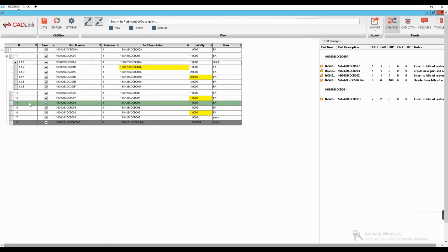So we have a gray line over here. This is a new item. That means this will be created in IFS later on. If we go into the unit of measure over here, there we can change the unit of measure. The drill down you see here is the drill down of the master data setup in IFS. So we only take data out of IFS to make sure that you get 100% quality of the data you are transferring from 3DExperience to IFS. So I select one over here, like the piece, and you see this display for the new item in that row.